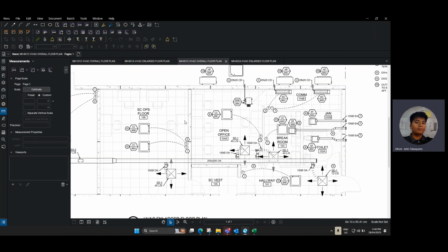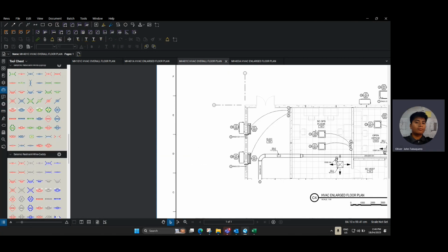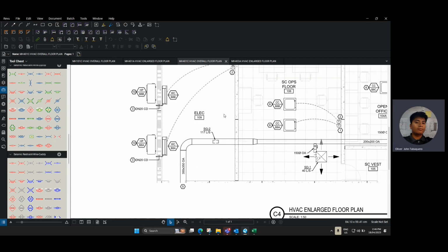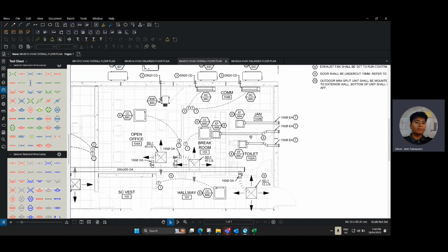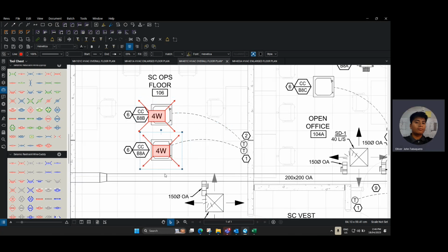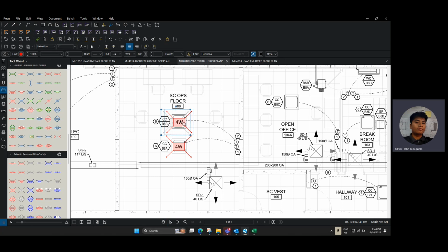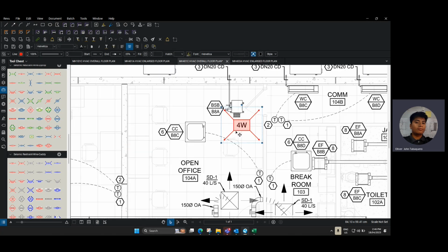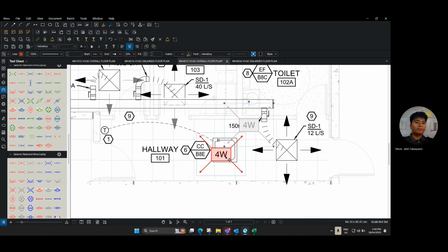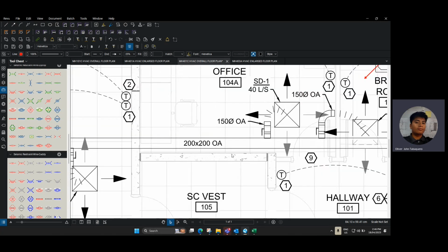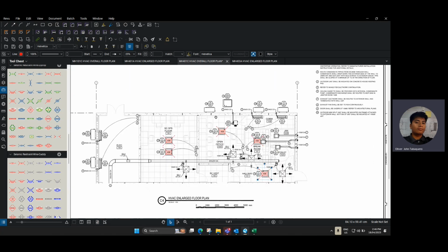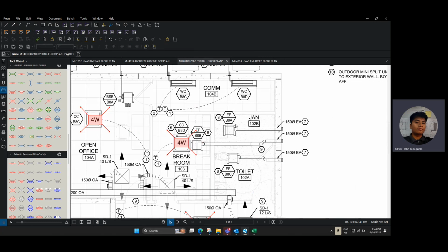Okay, we can start working on this. So here we have fans. We have fans and we have suspended ones. Oh, actually, yeah, we have fans here. Okay, so this is what we usually do. These are the cassette type AC units, and what we do is we suspend them as well since they are susceptible to falling in the event of an earthquake and they might injure someone, so we restrain them. As discussed earlier, this is less than 0.4, therefore not included, be it importance level 2 or 3. And these are small fans.